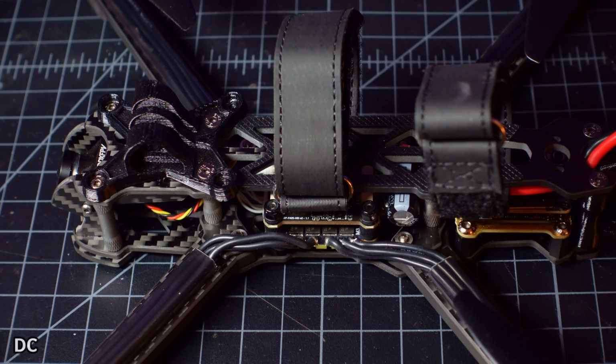If you want to physically do that, what you can do is, if you've built this quad yourself, you can swap 2 of the wires here with your soldering iron, and if you swap 2 of these wires, it will change the motor direction on the quad.